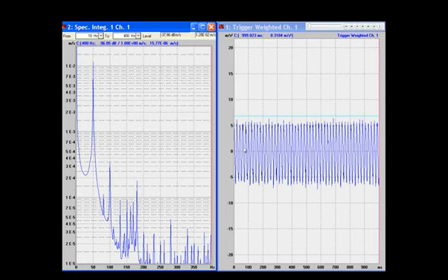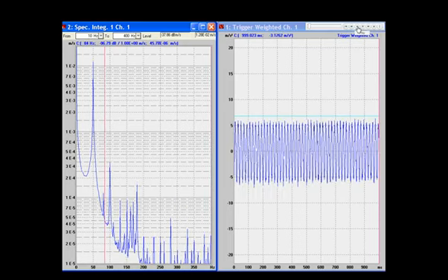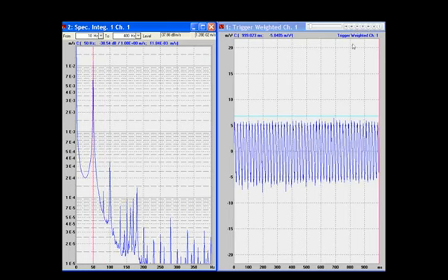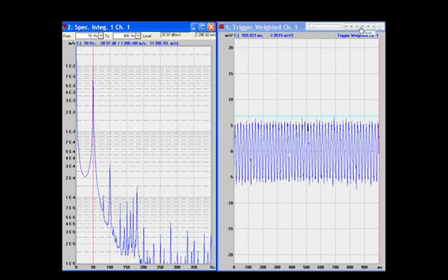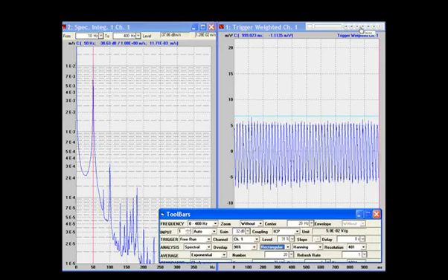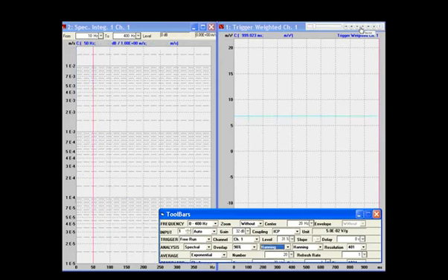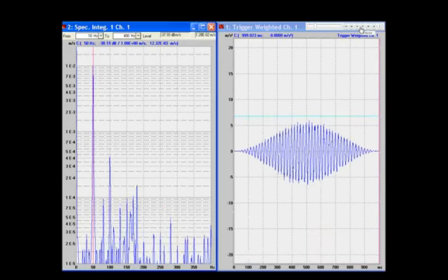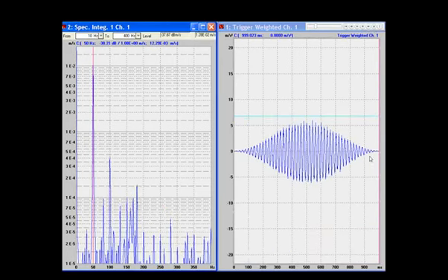So we need to cure that problem, and by far the most popular way of curing that problem is to use something called a Hanning weighting window. So what you're going to see me do on this video is I'm going to switch on some Hanning weighting. Lovely stuff. So the Hanning, mathematically, that's actually what you're doing to the signal.